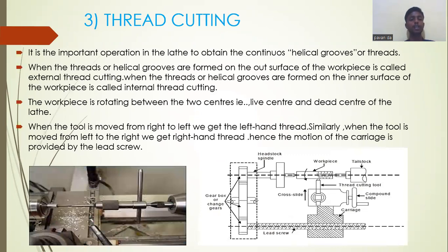And the third operation is thread cutting. It is the most important operation in the lathe to obtain continuous helical grooves or threads. When the threads or helical grooves are formed on the outer surface of the workpiece, it is called external thread cutting. When the threads or helical grooves are formed on the inner surface of the workpiece, it is called internal thread